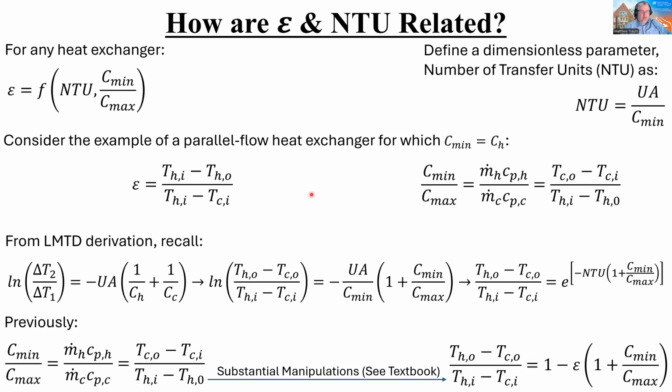It just kind of masks that extra complexity a little bit better because the correction factor for parallel or counterflow is just 1. So you don't have to worry about it for those most standard conventional configurations. But for Effectiveness-NTU, you have to do this for every single possible configuration, including the simple ones. And so a lot of students sort of get this sense that Effectiveness-NTU is more cumbersome. It's really not. It's just the complexity is more upfront. It's not hidden the way it is in the LMTD method.